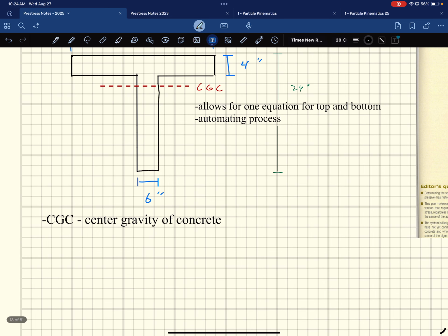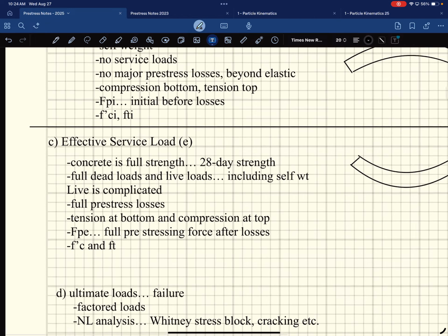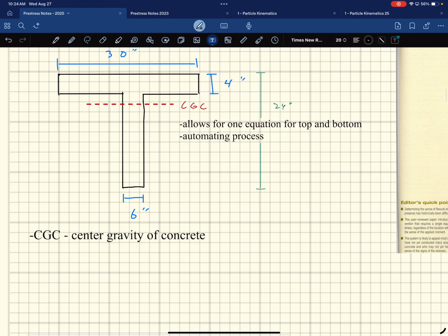Okay. How is that different from the neutral axis? Same. Neutral axis and center of gravity are the same in this case. Where they don't align is when things go nonlinear, right? When things go nonlinear, things get weird. That's where you have to figure out where your compression block is, your a, by setting the C equal to the T, and solving that. They don't align in the nonlinear range. In this, though, they align. Kind of, because the neutral axis means it doesn't move at all, okay? But we're pre-stressing this thing, so everything moves. Everything. So there's not really a neutral axis at all.